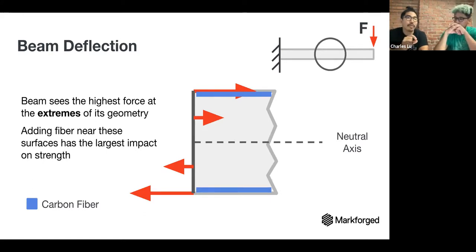If you were to add more infill versus add more roof and floor layers, you'd get different properties. If you wanted compressive properties for the part overall in the Z direction, I would add more infill, because the more dense, more material you have there, the more weight it can bear. You have the cell structure helping out there.